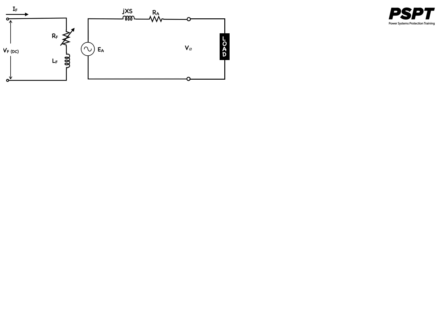Because the voltages in a synchronous generator are AC voltages, they are usually expressed as phasors or vectors. Since phasors have both magnitude and angle, the relationship between them must be expressed by a two-dimensional plot. When the per phase voltage EA, V phi, and jXSIA and RAIA and the current IA are plotted in this way, it will show the relationship among them. The resulting plot is called a phasor diagram.